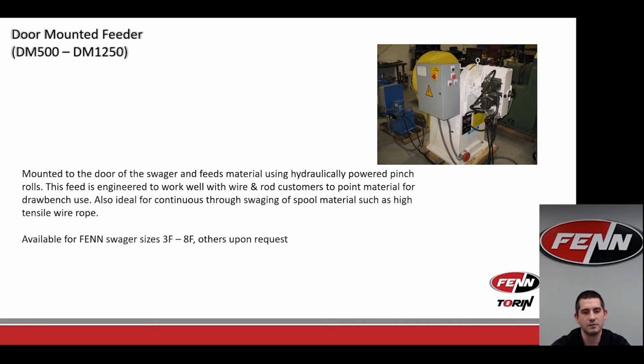Our door-mounted feeders. As mentioned, our door-mounted feeders are mounted right to the swager door, and it feeds material using a hydraulically powered pinch roller. This is used mainly by wire and rod customers that like to point material for jaw benches, or are doing continuous swaging with spool material such as high tensile wire rope.